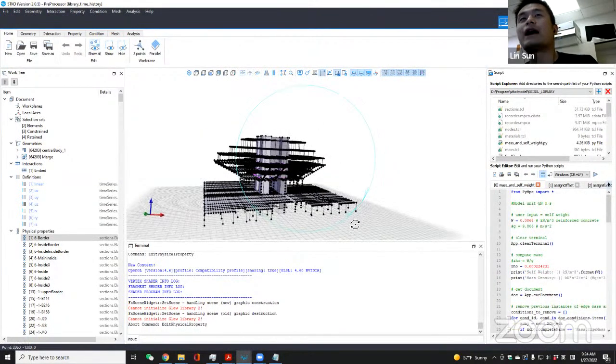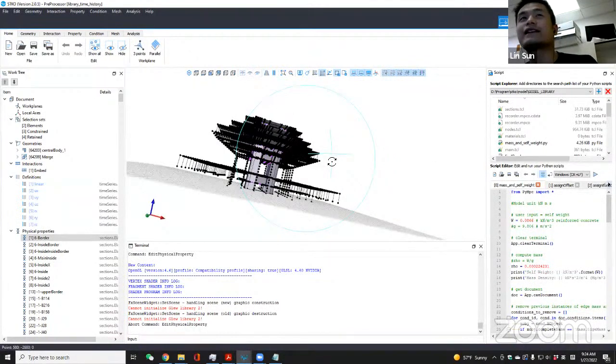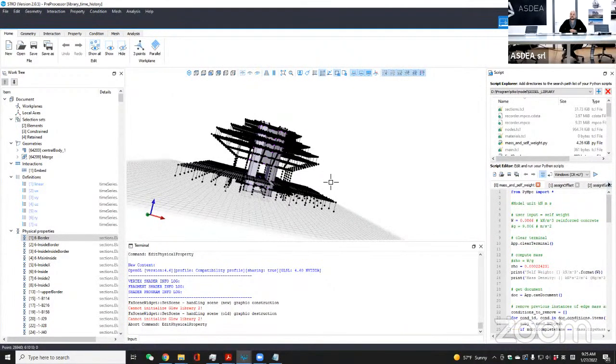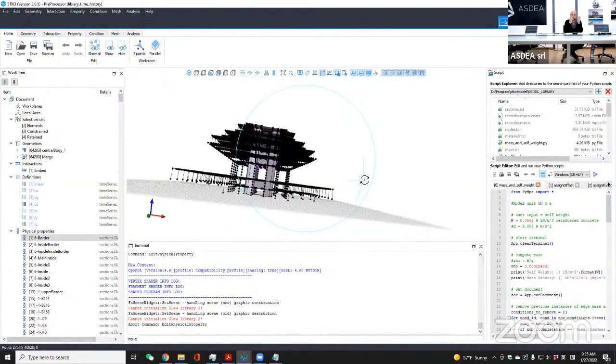Also, I don't want to use STKO because I'm using the supercomputer, which doesn't have STKO. They only have OpenSees. So if you can find an easier way to do this, it would be very helpful for me. Updating a parameter is actually a functionality inside OpenSees. So you can use STKO to access the setParameter command, and I will show you how you can do it. We will do it in a small model, of course, not on this one, otherwise it will take a little while.